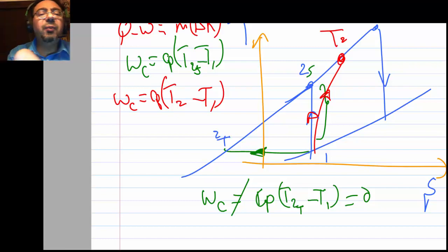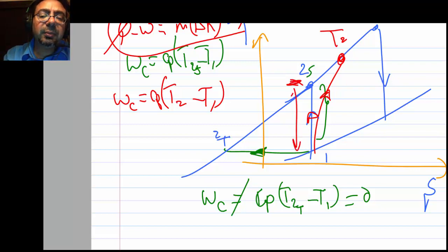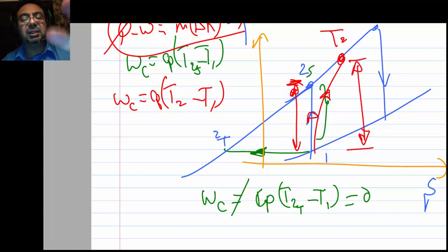It always comes from the energy equation, the first law of thermodynamics. So in case you are isentropic or adiabatic, there is no Q, and therefore the work becomes m dot delta h. And assuming constant Cp, m dot delta h becomes m dot Cp delta T, and you can basically say here is the work and here is the actual work, and you can really measure the distance and say that is the work because it's Cp delta T.